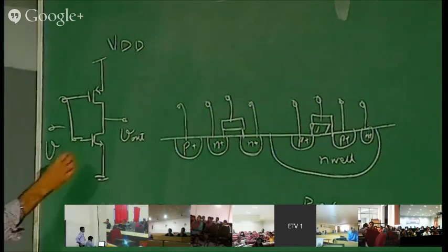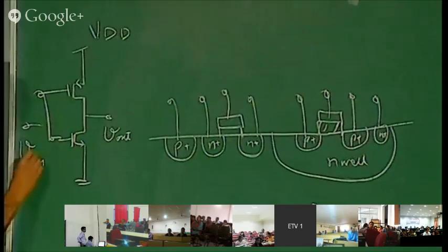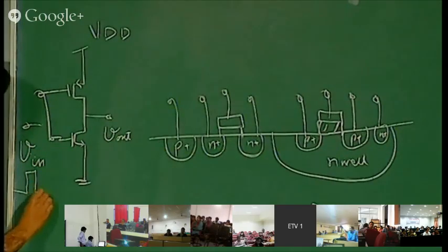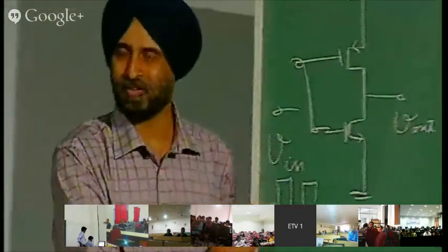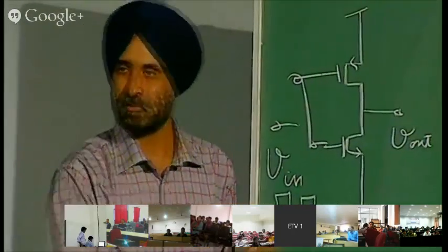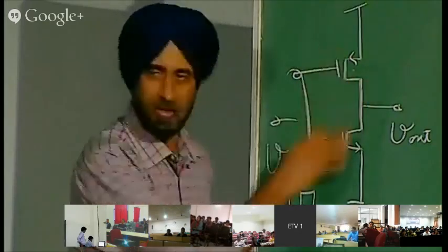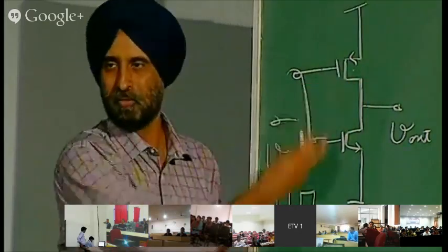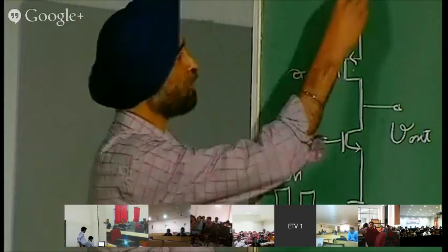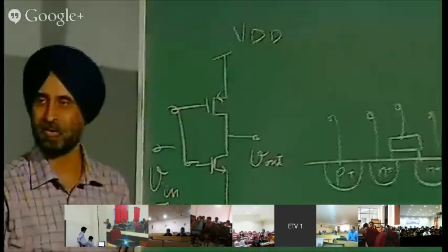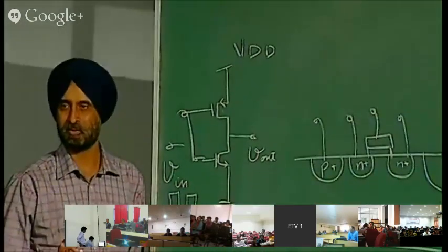Okay, so now when you take a clock here, the switching will occur. If this clock is not there, this means there is no clocking here. This transistor is off and this is on. Whatever, one will be off, another will be on. So from here to here, no current is flowing, so no power is consumed.